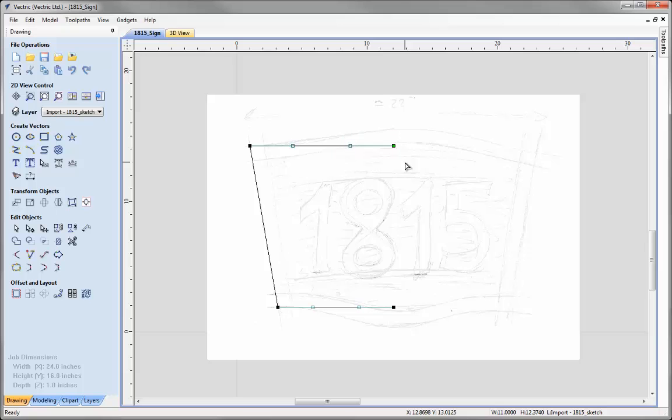And if I just drag a box around these two nodes and shift and drag a box around these two nodes, with the old version, I could easily move those up and down so that they remained in sync with each other using the arrow keys on the keyboard. However, now I've got the option while in node editing to hit V or H to do vertical or horizontal symmetry. In this case, I want vertical symmetry, so I'd hit V on the keyboard.